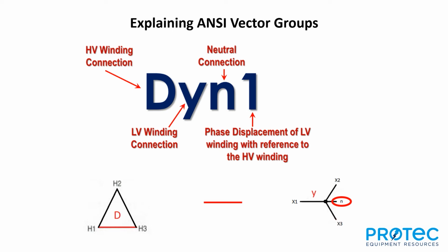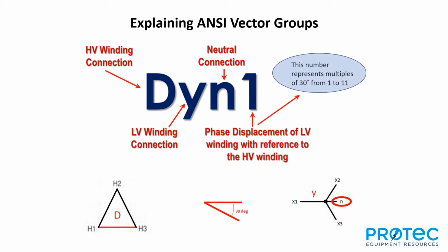So all of our references have to be back to the primary winding, and because the primary is a phase-to-phase voltage, that's what we want to compare to on the secondary side of the transformer. And so if we take that and overlay it in reference to the primary side, we see that there's a 30-degree shift between the two.